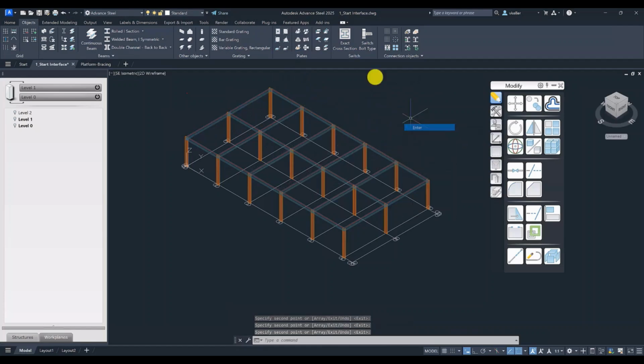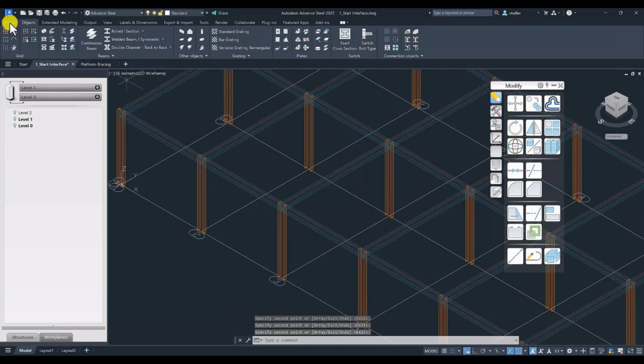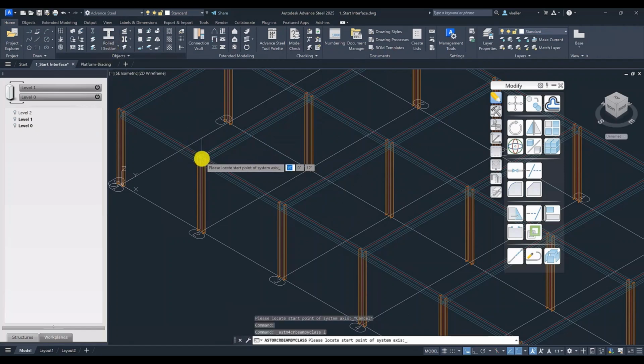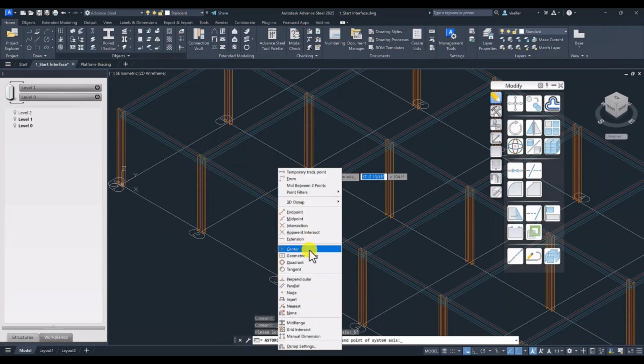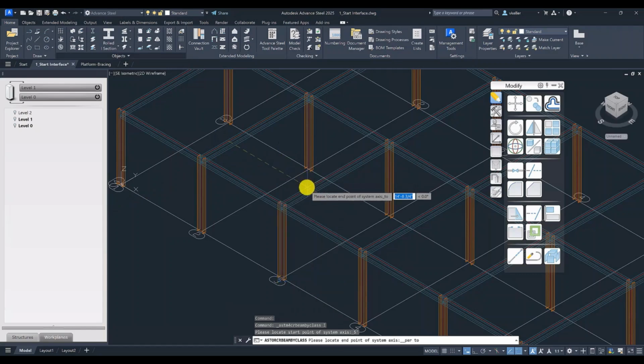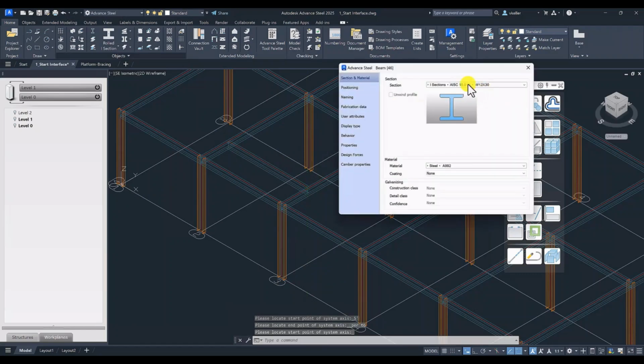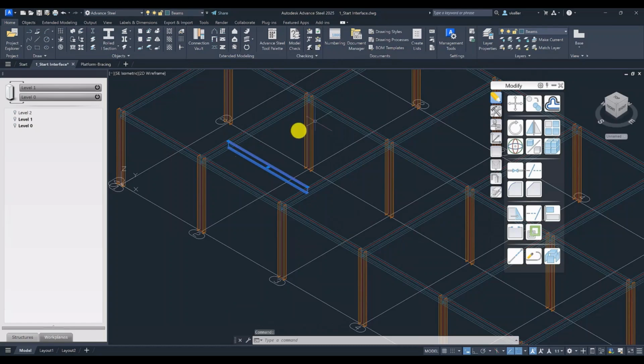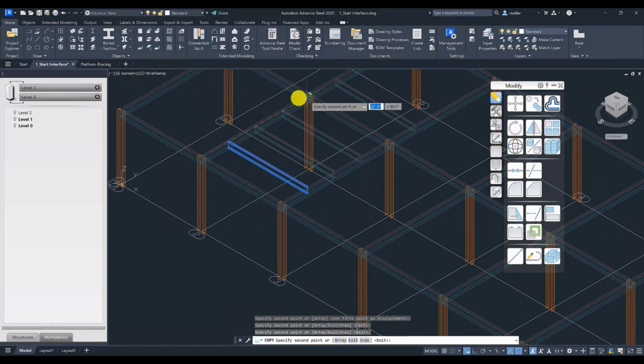All right, individual. Now, I have in here a project a little more down in here. But before I do that, if I want to place some pieces inside of here, I might track it out, put one in all by itself. Sometimes I draw construction lines, like line work, because I can convert lines into beams, polylines into beams, which can be very useful too if it's a very complex type of model. Choose one of those, guess what? I'm going to copy it. But we're doing these as individual pieces. Yeah, and that's how we do it inside of Advanced Steel.